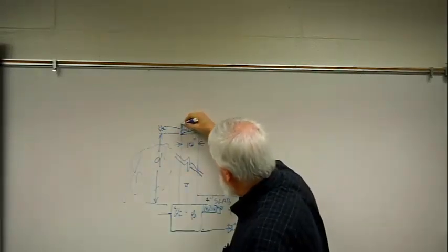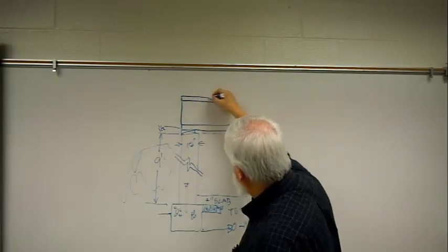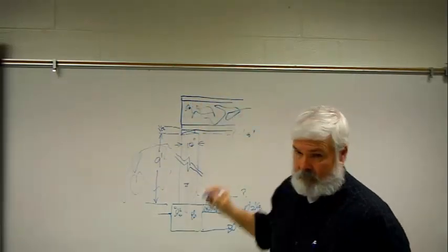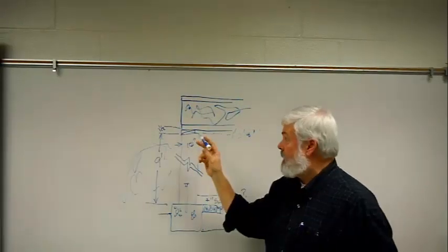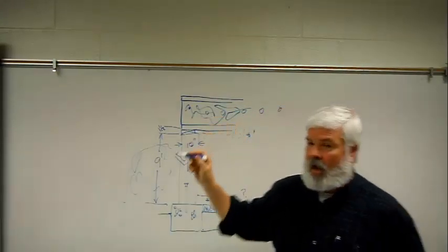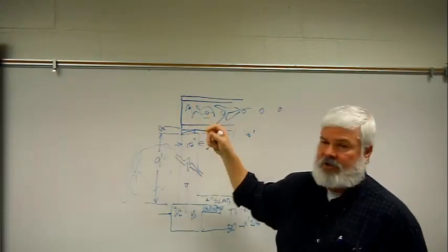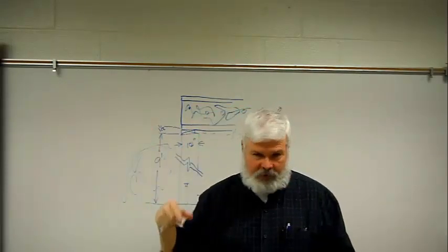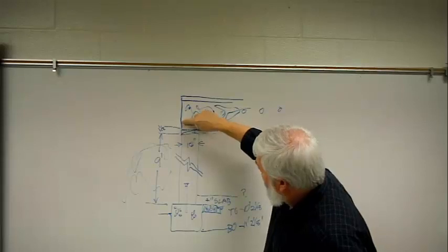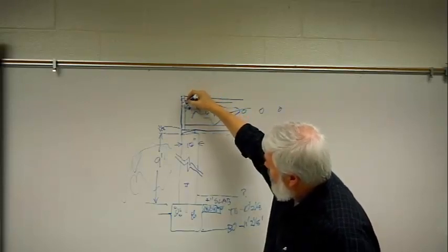So what we have sitting on top of this now is an I-joist, which is 11 7/8 inches. And I'm drawing it like that because it has the top strand and the bottom strand, and then it has the wafer board in between. And just an interesting little structural note about I-joists is the material typically has little knockouts that you can just tap with a hammer, and this inside wafer board, or OSB, will knock out so the electricians have a hole that they can run electrical wires through without having to drill. But what's interesting about these is their strength, and I need to add one thing to my little illustration of this wall. I need to have that band. And the band can also be plywood.